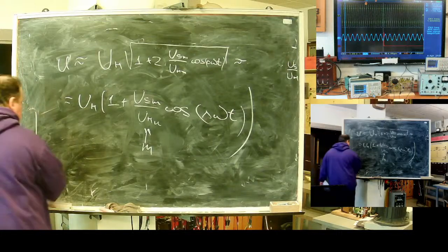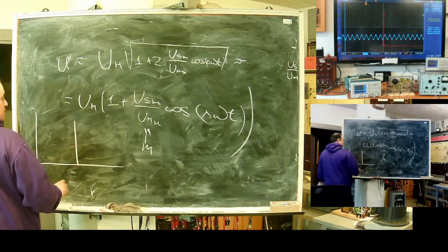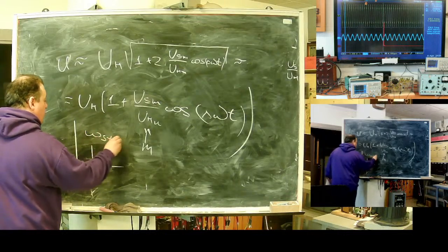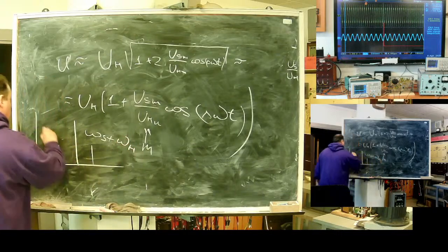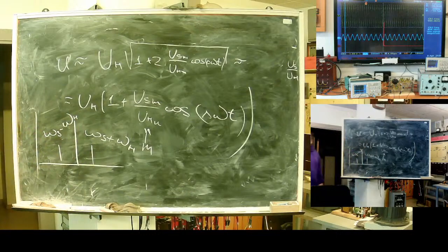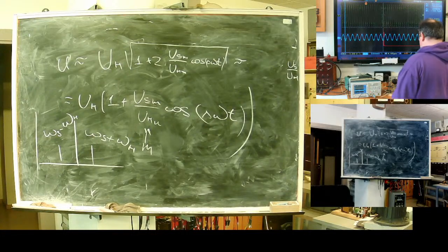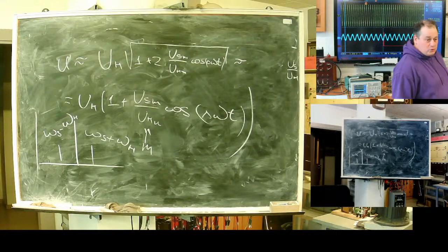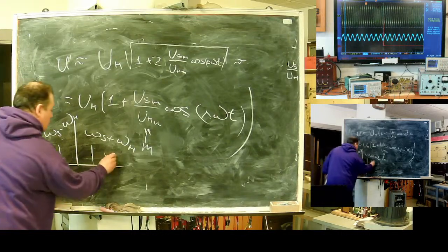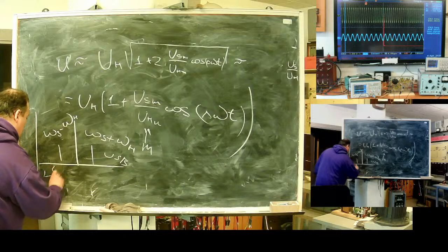They will have omega signal plus omega heterodyne, omega signal minus omega heterodyne. Yeah? Sidebands. You missed it. And you missed amplitude modulated signals. Those who saw amplitude modulated signals and the spectral diagram, what do we have? USB and LSB.